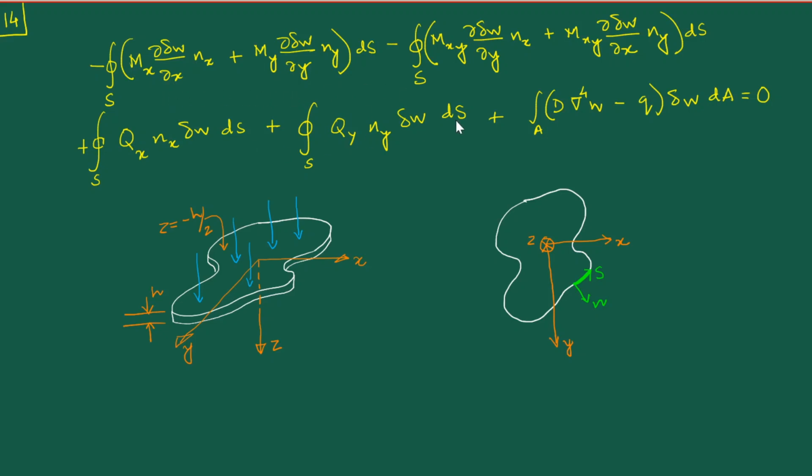So none of these terms explicitly contain any integration with respect to z. That has already been taken care of or absorbed within the terms. So all that is left is a consideration over this domain, as if we are only concentrating on the flat mid surface of this plate.